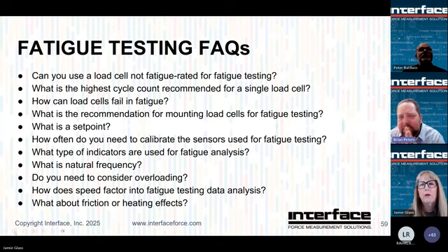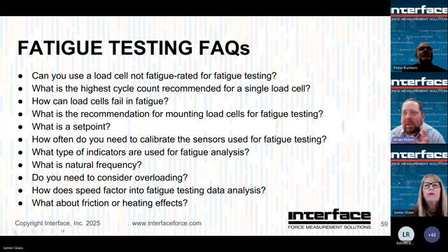Was there another part to that question? Something about a cable? You had mentioned the strain relief for the cable plugged in. Is that the cable plugged into the load cell? Yes. So you'll have a cable. You'll either have a mating cable that plugs into a connector on the load cell, or you'll have an integral cable coming out of the load cell.